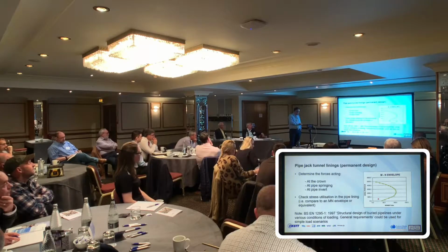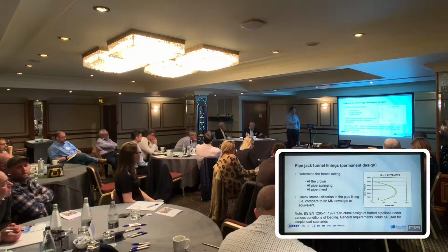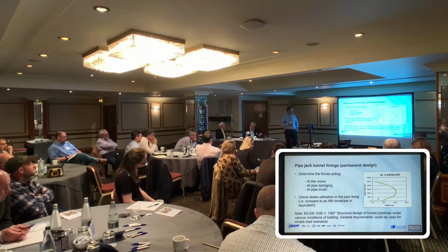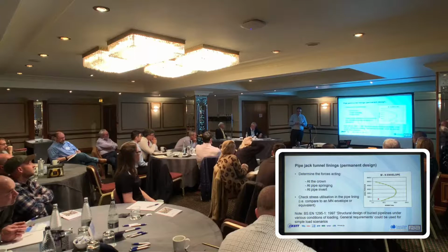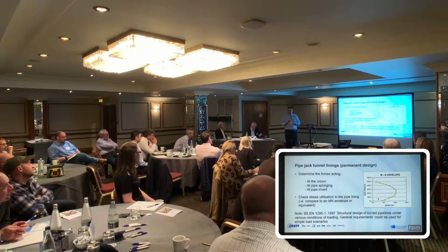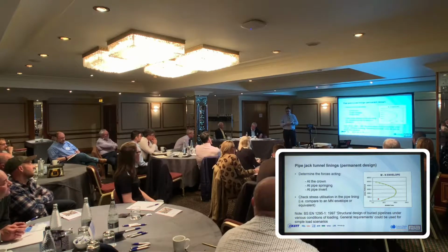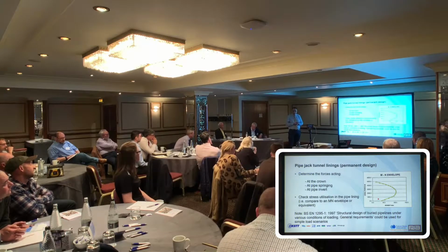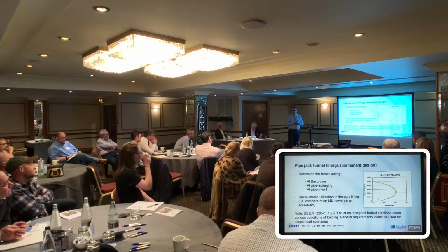I've just put that note at the bottom. This is, if you like, the first principles way. But at the bottom there, again, 1295 considers buried pipes. It has a formula to calculate the effects of earth load, water, surcharge from construction, and surcharge from railways. But that document was designed predominantly for open cut methods.